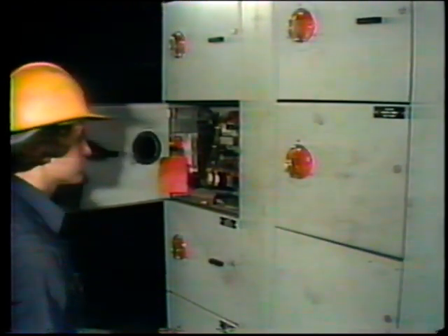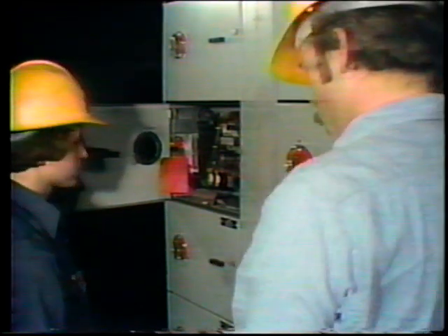After testing for grounds, the electrician tests for shorts. He'll begin by testing the operating coil. A multimeter is used to test for shorts. It must be set to the resistance scale. The electrician disconnects one lead from the operating coil to prevent a parallel current path.